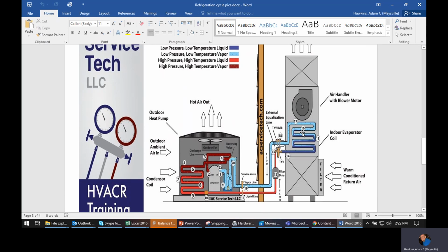So here on this picture, this 0.16 would be the point at which it becomes vapor. Now, once it becomes vapor, the latent change is gone. So that's where the latent change stops. And so what we've mentioned in the past is that you can't latent and sensibly change something at the same time. So it's either latent or sensible. So from the time it leaves the TXV until it completely vaporizes, that's all latent. That's what's doing all the work, because that's the evaporation process. So that's where we're picking up all that heat. That's what has all that capacity to grab all that heat and capture it just through the changing of state.